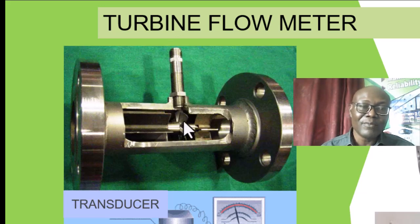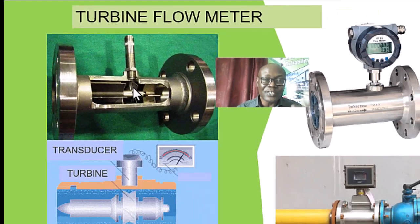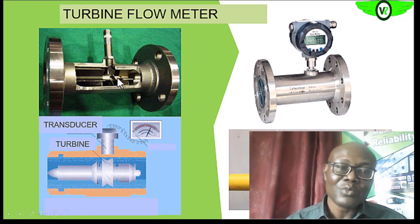So in the turbine flow meter, we have a turbine in it that turns when it is impinged upon. That is, when the fluid flowing through the pipe strikes it, it turns it. Okay, so the number of pulses, like we said earlier, increases with the flow rate across this section of the pipeline. So this will, at the end of the day, give us the volumetric flow rate.